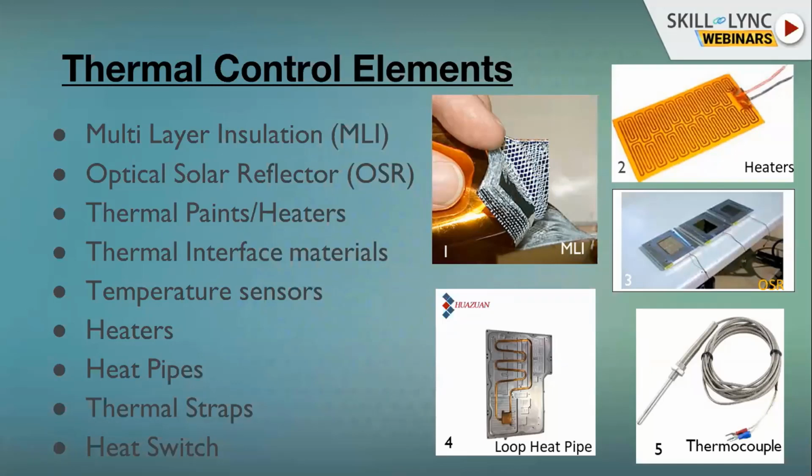First there is a layer of aluminized Mylar sheet, then a Dacron netting, and then again an aluminized sheet. The purpose of this arrangement is that with the Dacron netting in between, the only mode of heat transfer between the two aluminized sheets is radiation. Depending upon what kind of conductance you need, the number of layers in the multi-layer insulation can vary from 5 to 30.